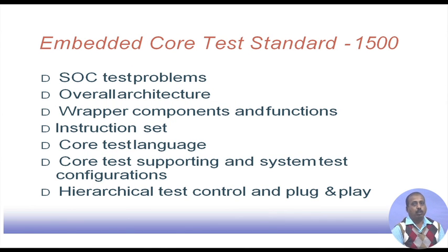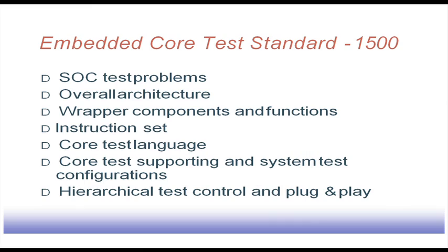So that talks about the 1149.1 standard. There is another standard, 1149.6, which we do not discuss in detail in this course, because that is some extension: it supports a high speed test bus, and it has an analog interface and things like that. So some augmentations have been done. Rather, we will look into another standard for embedded core test, which is known as the 1500 standard.